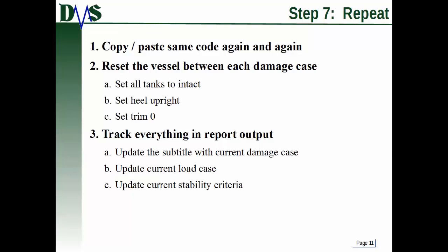Now, since you're copying and pasting things, one of the things you really want to make sure is to completely reset your vessel between every single damage case. So you're going to want to set all of your tanks to the intact condition. You're going to explicitly tell your vessel that it has a heel of 0, that's upright. You're going to set the trim to 0 as well, and possibly re-equalize the vessel as well before you apply your damage cases again.